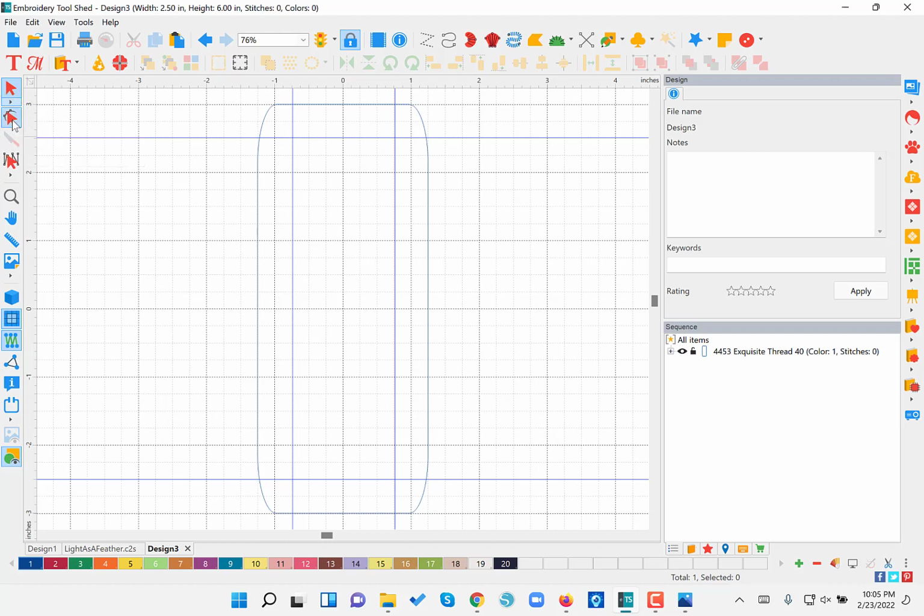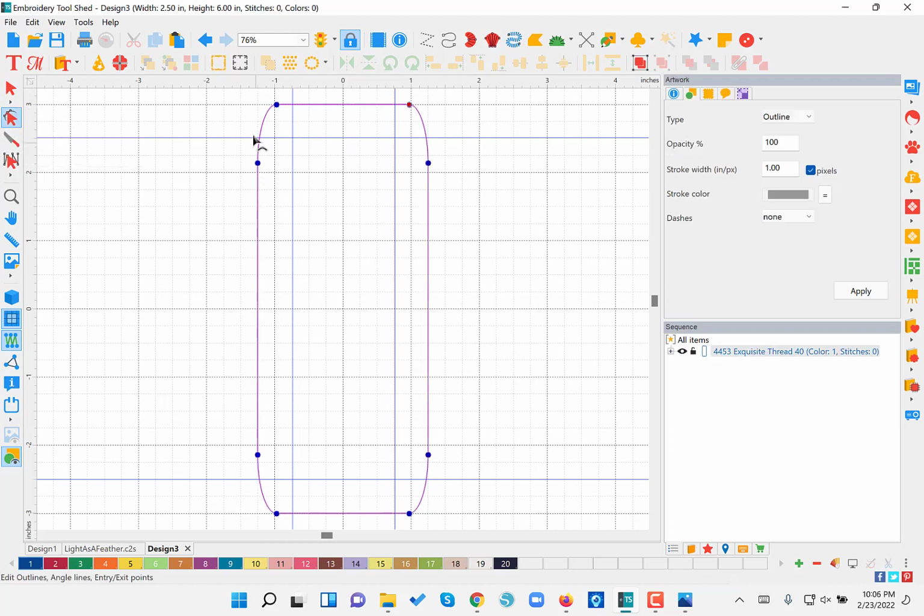Okay, so I'm going to go over here and click my shape tool, and I'm going to move these points to line up at the intersection here with this particular line and here. Okay, so click and drag these points, and it'll snap to that guideline into the grid, and then I'm going to click and drag over here. Same thing, it snaps to that, and then move these points too. So let's move this one first because that one has a stop on it. So the red means that there's a stop, so whenever you move that out of the way, you'll be able to get to the actual point. So click and drag over to your line, and now I can do a right mouse click to set those, and we see what our curve is like.